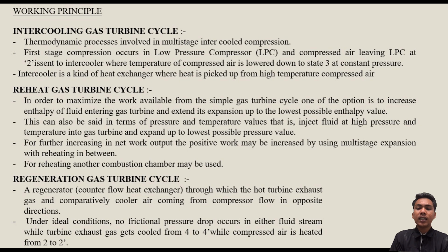Next, for further increase in net work output, the positive work may be increased by using multi-stage expansion with reheating in between. For reheating, another combustion chamber may be used.